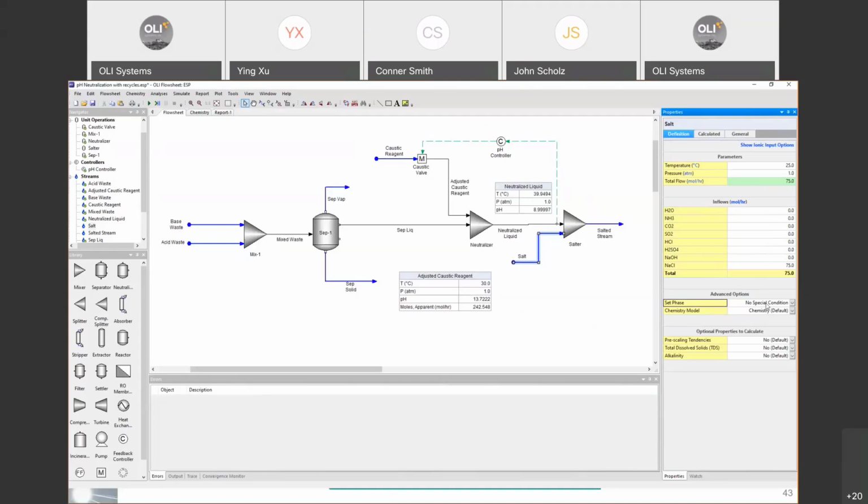So we go to the option set phase. You see that there are a lot of options. You can define if it's a liquid 1 and solid only, vapor only, no vapor, liquid 2, etc. For this example, it's a solid only, and that's what we're going to tell the software. Select the option solid only. And what this does is that it will reduce the calculation time, since the other phases will not be included for calculations. So it will be only solid phase, and that's it. It doesn't need to calculate aqueous properties, vapor, nothing of those equilibriums will be considered.